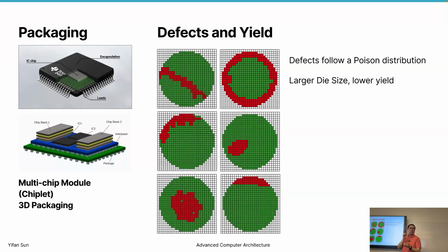And especially when we have smaller and smaller transistors, the yield is getting lower and lower. So if we build a wafer and many of the chips we have to discard, the cost of manufacturing a chip is rising, right? But consider where this dust falls, it's a distribution. It follows something like a Gaussian distribution or a 2D Poisson distribution.